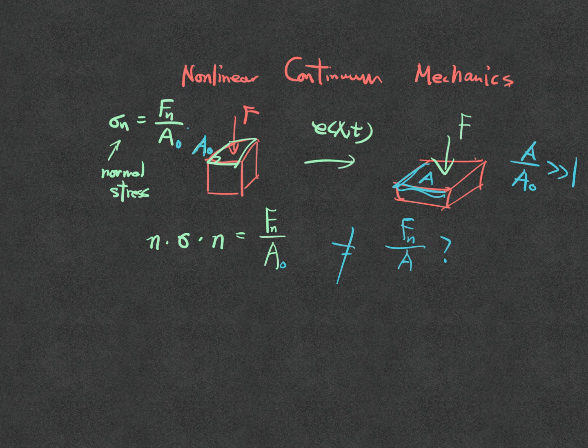So nonlinear continuum mechanics is necessary when the material is very soft, or when you apply a very large force to it. For example, if you want to model plastic surgery or anything to do with soft tissue, or food processing in finite element or whatever that deals with very soft material, then large deformation continuum mechanics is necessary. But for rock mechanics, for things that are very brittle, very hard, it is less necessary. Okay, so let's take a 10 minute break and I will come back.